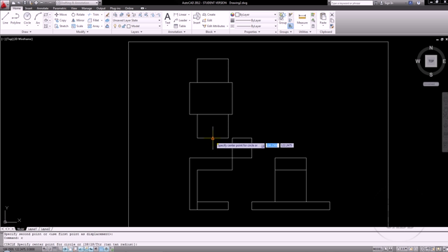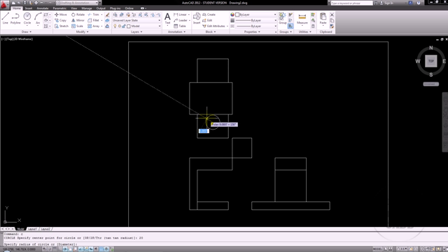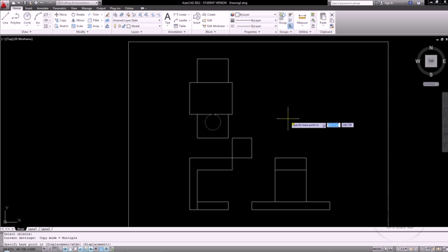So what I'm going to do first is draw my first small circle, which is going to be projected off of here 20. After projecting off of there 20, I want to make the diameter also 20. Now I'm going to copy this, and I'm going to copy it in the direction up 30 and 60. And what that's going to do is create those three holes for me.